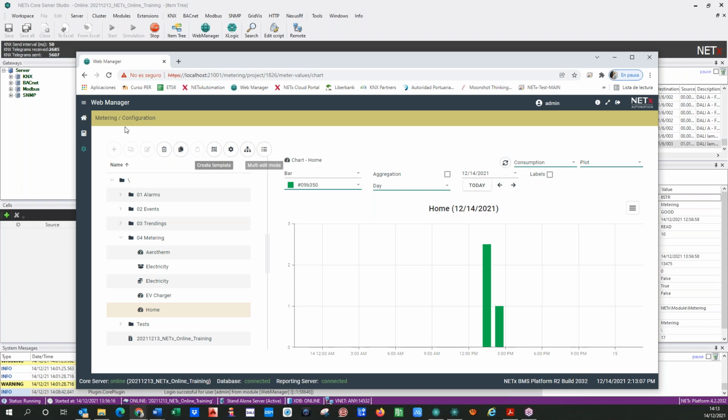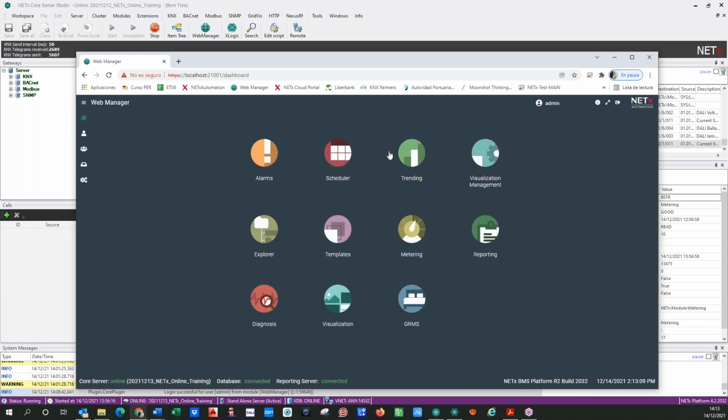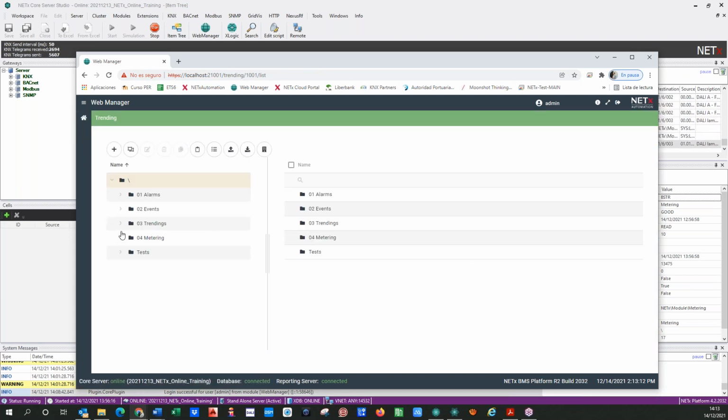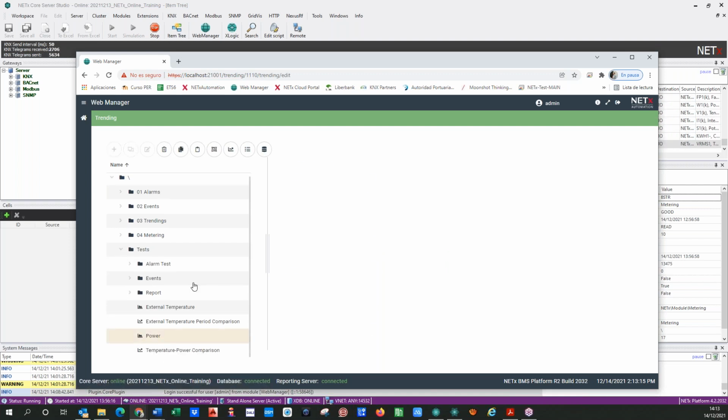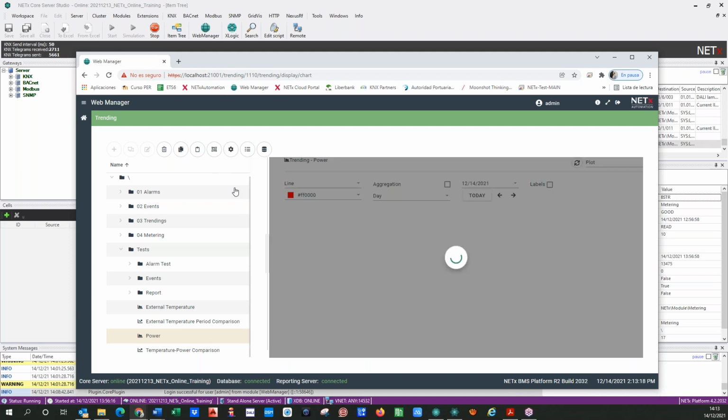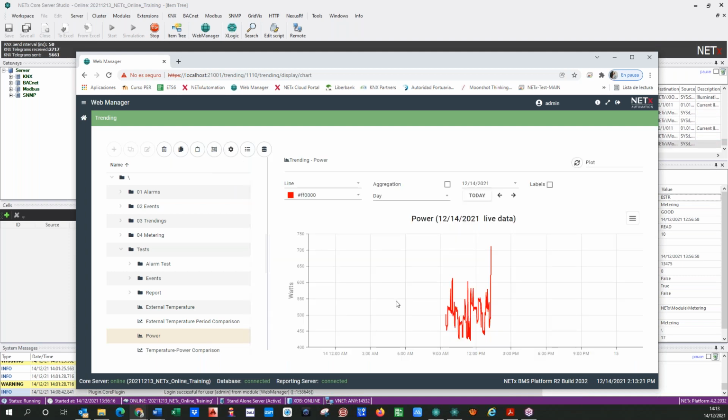This is very important, because sometimes we have a bit confusion between what is the power and what is the energy. So if you use, for example, the trending that I used before in the test as a power, this is not the right decision. This is not for the energy. The energy is a result of the power, but this is a different calculation, and it is a different measurement. So don't use power, use energy consumption. If you don't have that, you need a measure, or you need an estimation. You can use the LAMPS module to estimate that, okay?